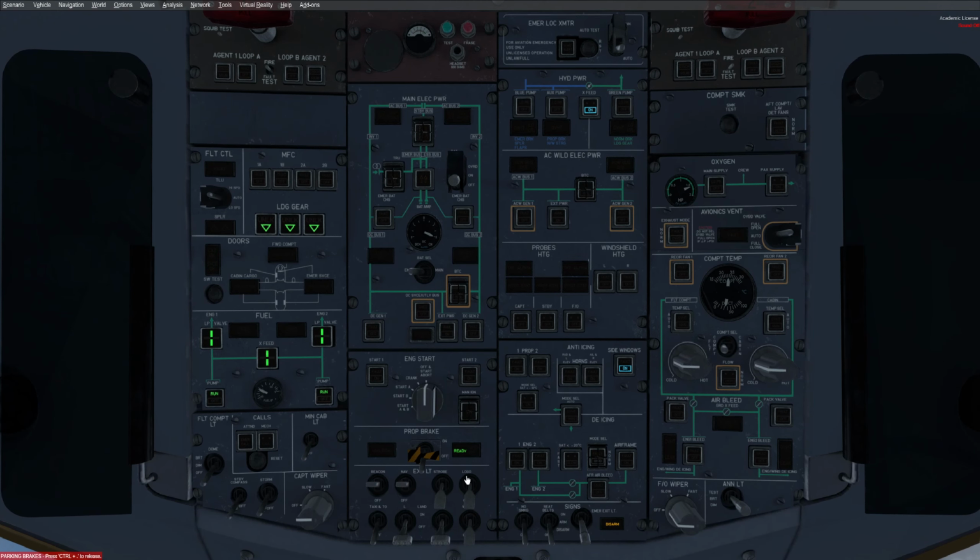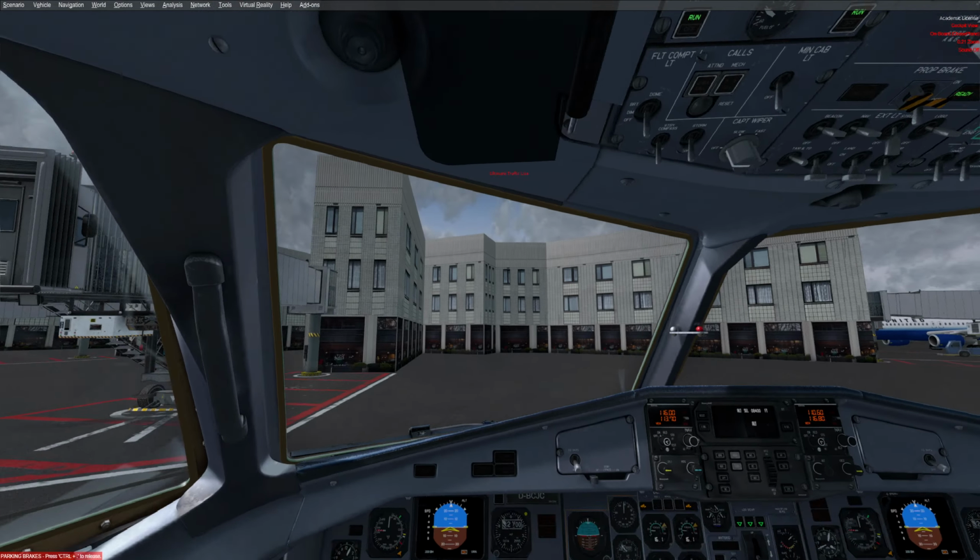Oh, we might as well nav, logo, wing. Well, we don't need wing light unless we're looking for some ice. Taxi takeoff. That's what your taxi light is. Your landing lights are here. This is a nose light, and this comes off the wider wing area there, and it's really bright for landing and that kind of stuff, takeoffs. I think the rest of it up above looks good. That's the last stop up there.